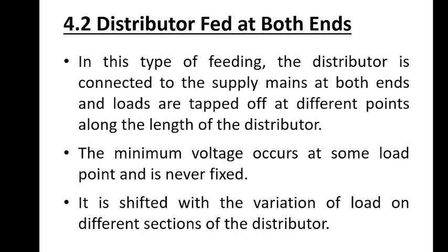Unlike the single-end feeding system, the voltage profile in this case is more balanced, and the minimum voltage does not necessarily occur at the far end. Instead, it appears at a certain point along the distributor, depending on how the loads are distributed.